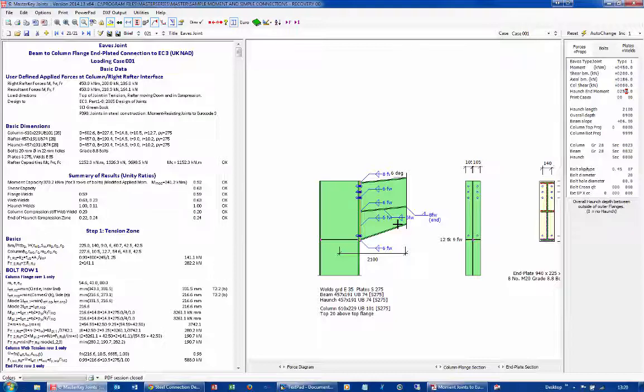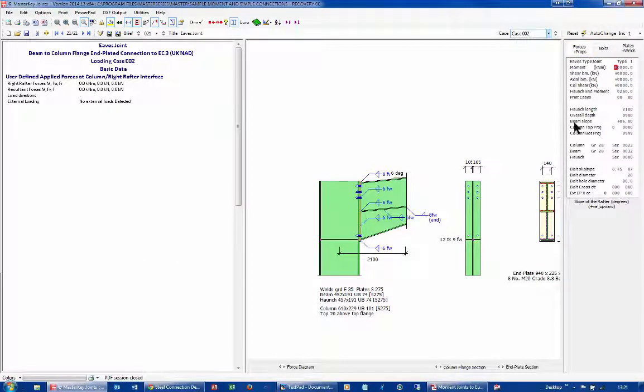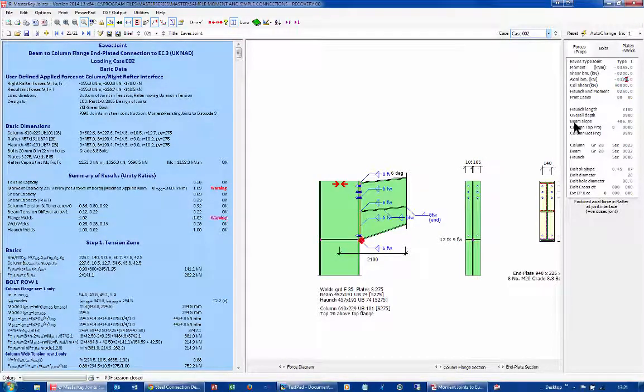Obviously joints don't have just one loading case, so I'm going to put in a reversal case, and I'm going to put in a negative load of 355, a shear negative of 200, an axial in tension, which is detrimental, of 175. So I've now got 67% overstressing and 2% on the flange welds, because I put that weaker weld down there.